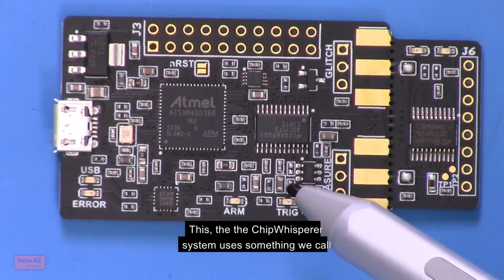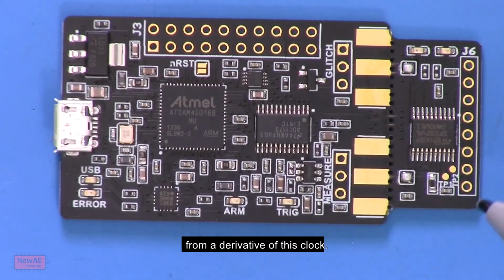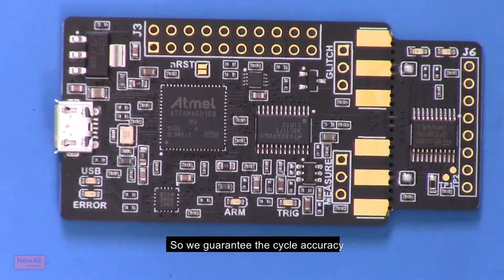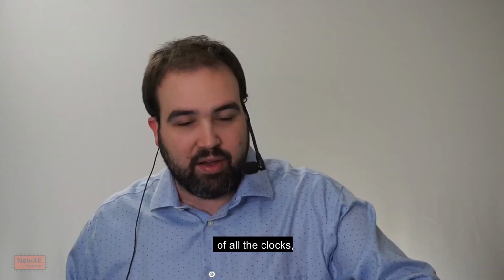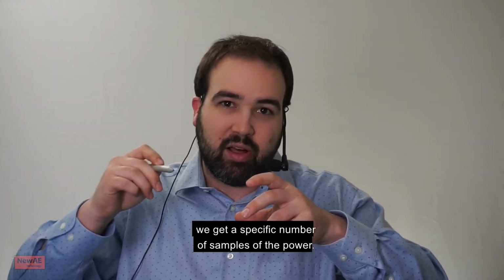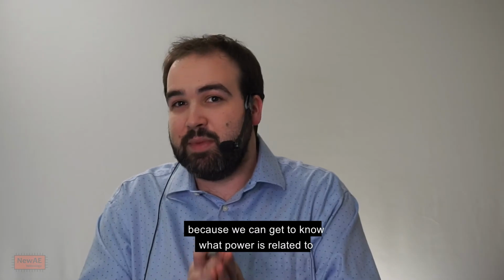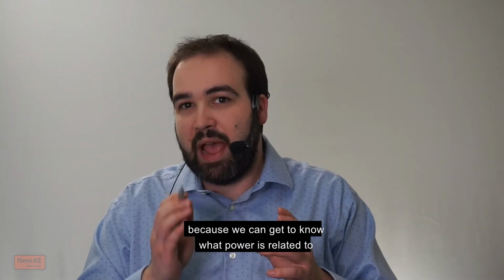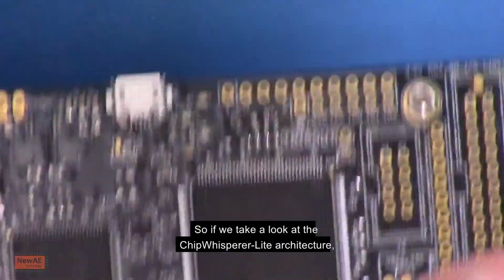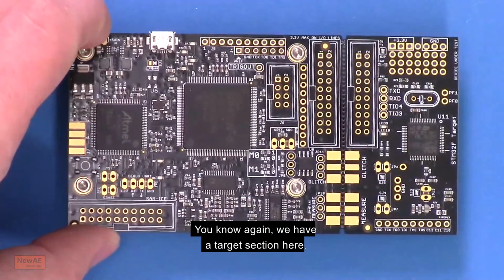The ChipWhisperer system uses something we call synchronous sampling. This means that this device is actually clocked from a derivative of this clock, so we guarantee the cycle accuracy of all the clocks. Everything's done in lockstep. So for one cycle of the target clock, we get a specific number of samples of the power. This is very handy because we can know what power is related to what's actually happening on the device. If we take a look at the ChipWhisperer Lite architecture, it's similar.